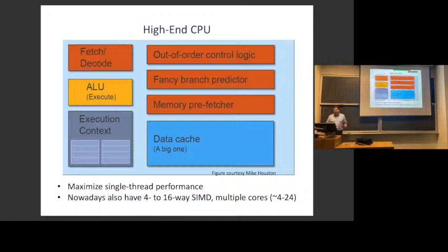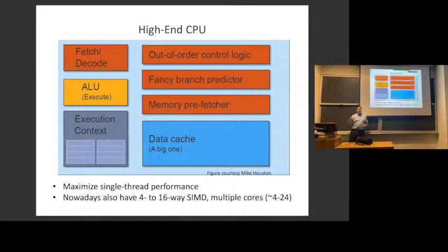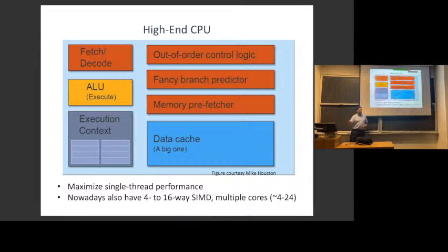That's a lot of cycles, especially if the processor can actually launch 4 instructions for every cycle. So if you actually waited for data to come back, you stalled the whole processor, you had several hundred instructions that could have issued in that time. So you don't want to do that. So the memory prefetcher is trying to, even if you're accessing large arrays, guess what you're doing next. It's tricky, because if it guesses wrong, it actually might take stuff out of the cache that you need later. So it can't do a perfect job.